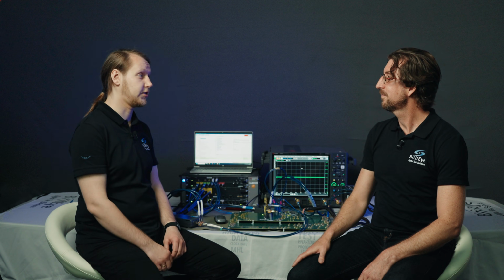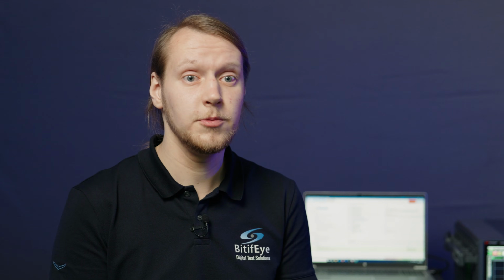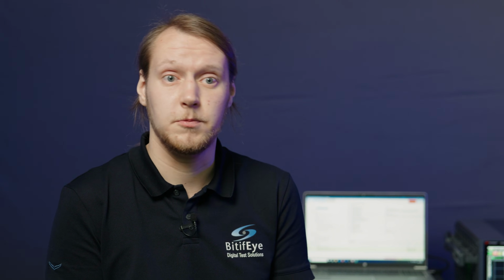That's a really good question. To make sure we are only capturing errors in the back channel, we let the DUT transmit a known pattern. By default, we toggle the DUT into the correct PCIe TX compliance pattern, fully automated.